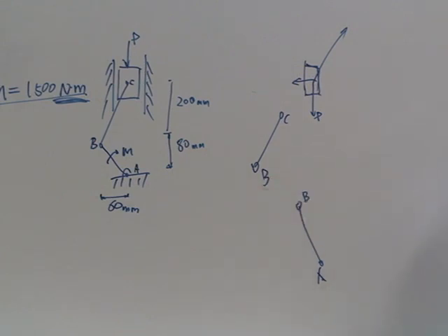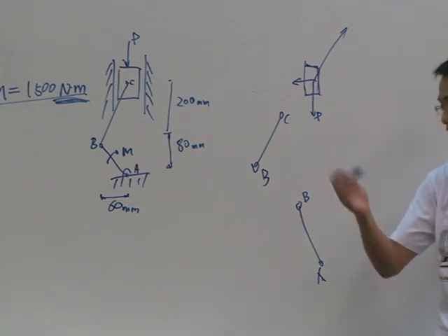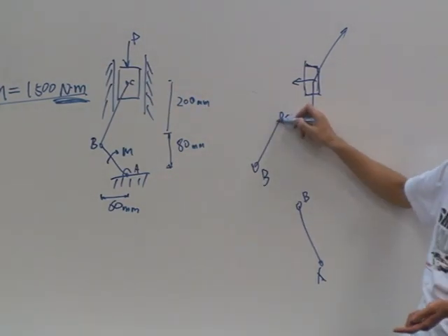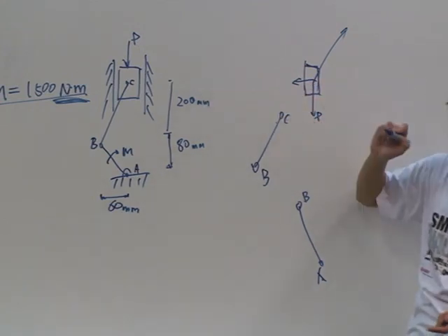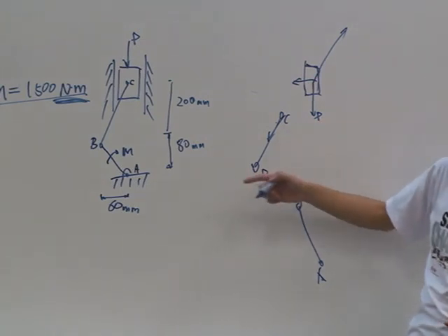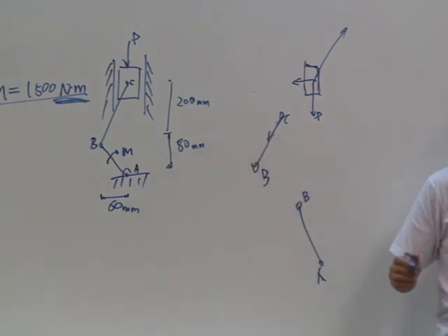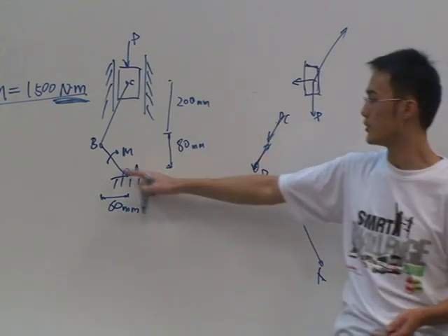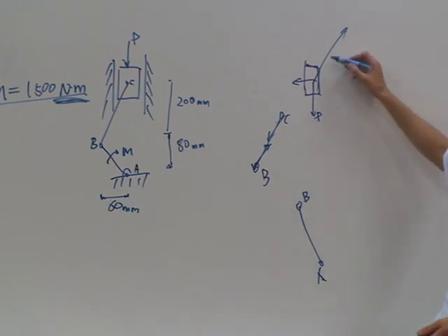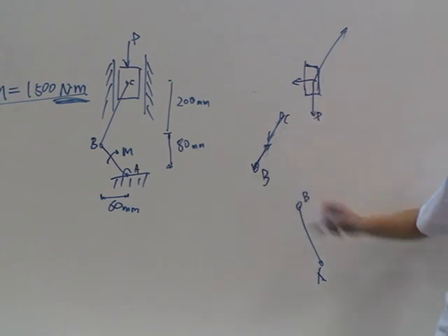For the second, actually we don't need to analyze so much, because straightforwardly we know that the force is all inside this axis. Since it gives a force to this piston of this direction, this slider gives another counter force of this direction. In other words, because it maintains static equilibrium, there will be a force from BA in the axial direction as well, of the same magnitude as this one.